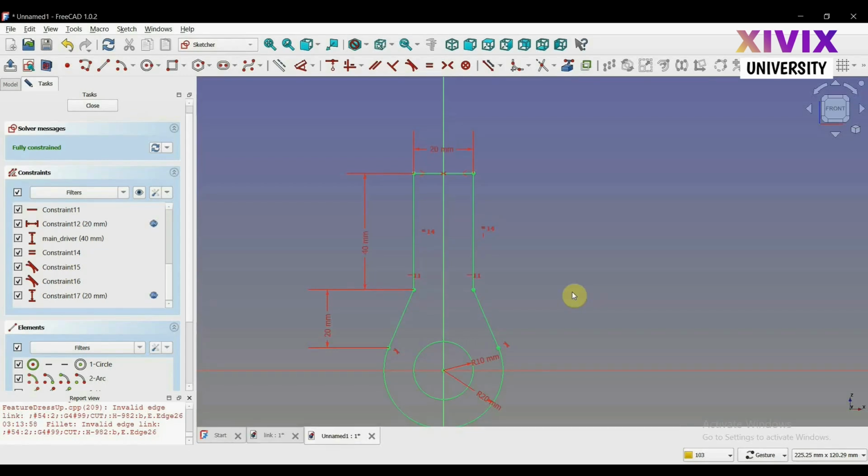And the most important thing that you must know is that you have to anchor the sketch into the origin, either the X, Y, or Z plane that you're working on, because they are embedded into the original coordinate system, and the coordinate system is the engine behind all these geometric constraints and everything you do.